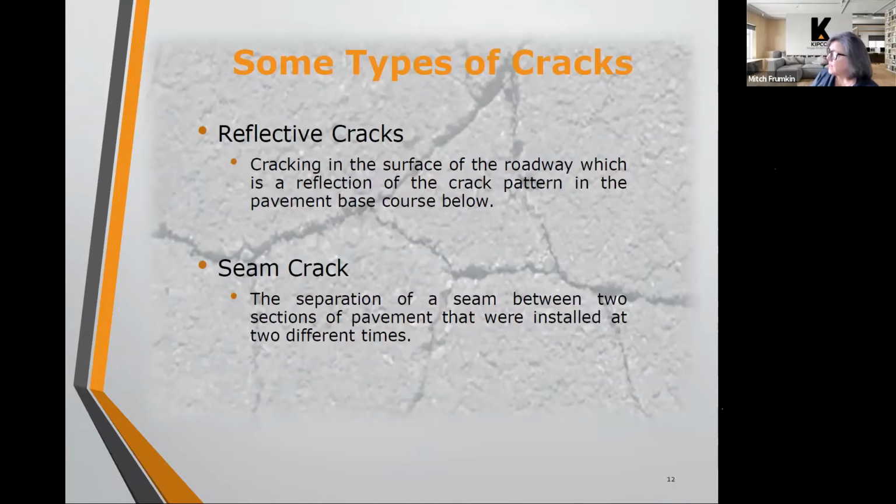They are often in areas where a parking bay may meet the main roadway. You see cracks open up along the front of those parking bays a lot. That's because there's a seam there from when the original pavement was installed. And with shrinkage over time, and then with water flowing along that flow line, that crack opens more and more each year.